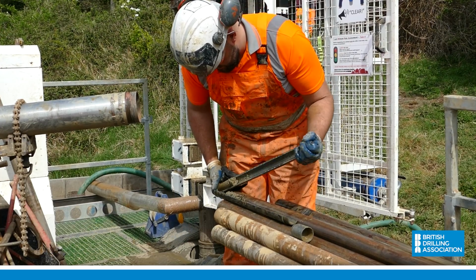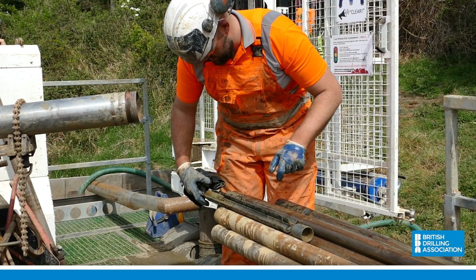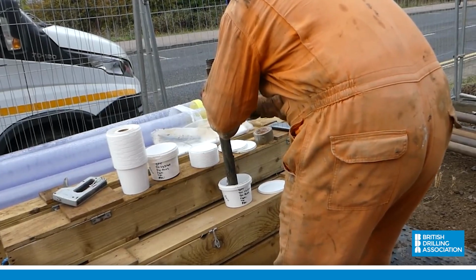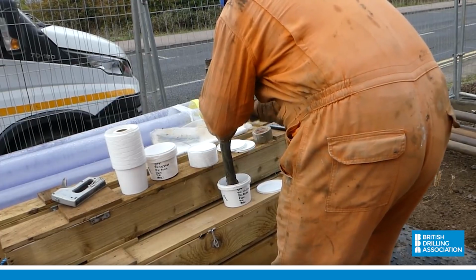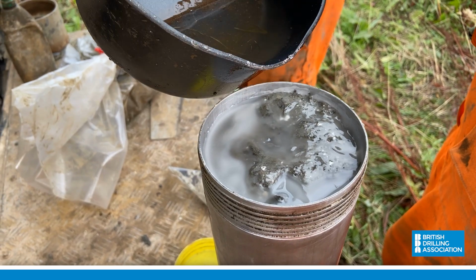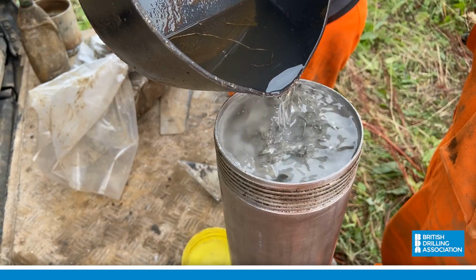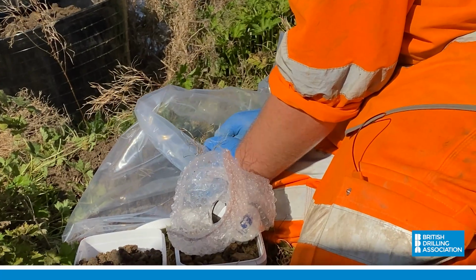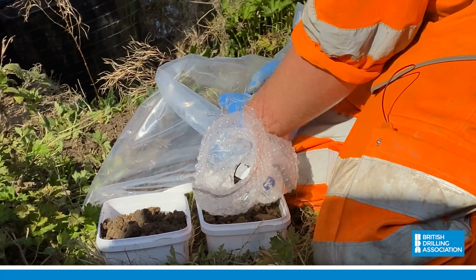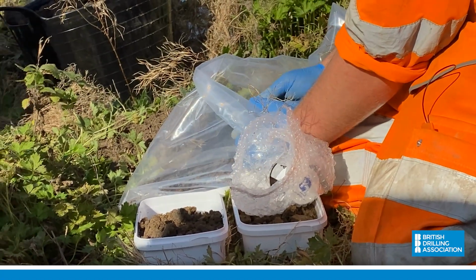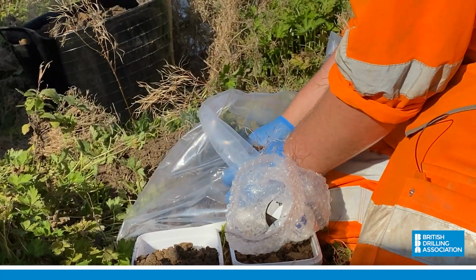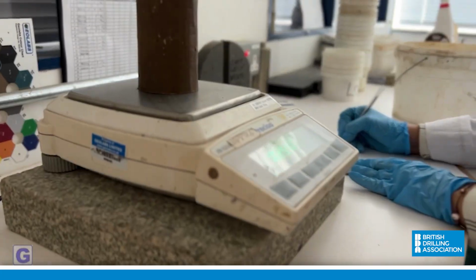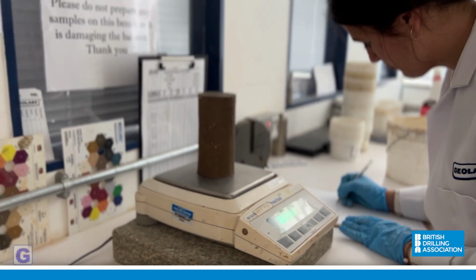After retrieval from the borehole, the sampling equipment has to be carefully separated from the rest of the drilling assembly and the sample removed. Whether it is a sample of soil or water, it should always be placed into an appropriate container that is sealable in order to maintain the conditions of the sample. When it comes to laboratory testing of the samples, if they have been removed from their original environment and not contained in a sealed environment, changes in the sample's makeup can occur that fundamentally alter the results obtainable by the laboratory.